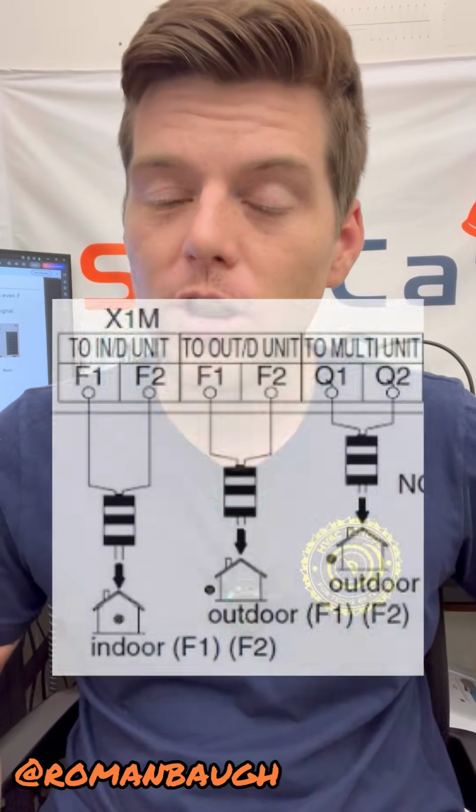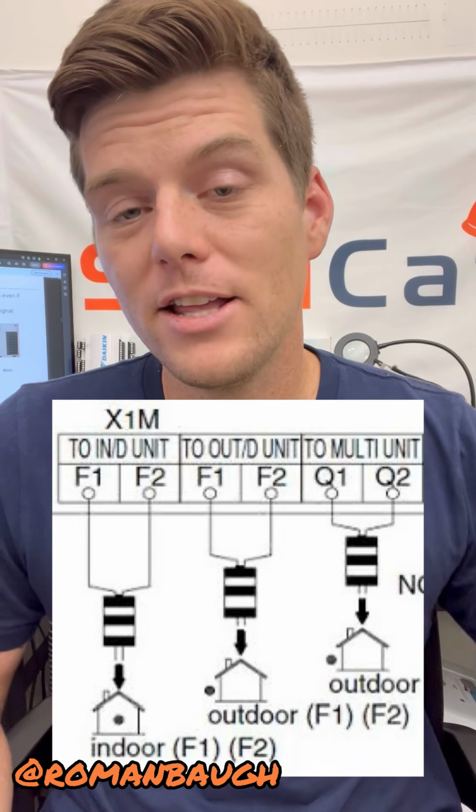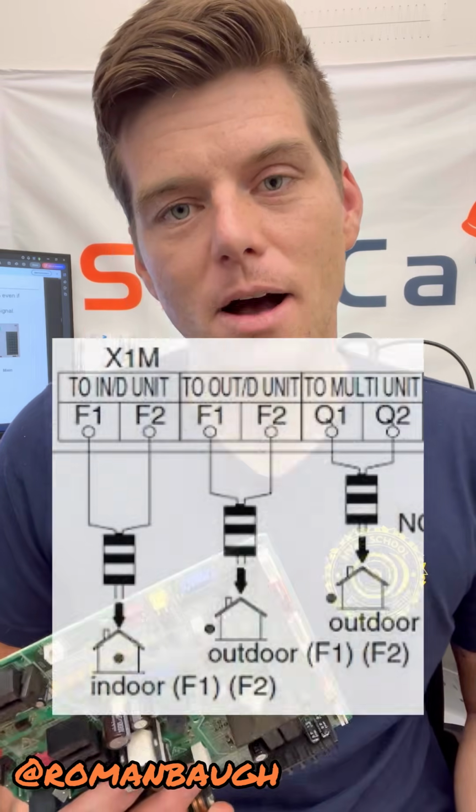Why is that important to understand? Because they're separate communication circuits, you can't just land your service checker wherever you want to and pull in all the information points. It's just not going to work that way. So when we're looking at heat recovery systems, it's important to connect either at the outdoor unit or in the F1, F2 in circuit between the outdoor unit and the BS box. Otherwise, you're not going to pull all that information in.